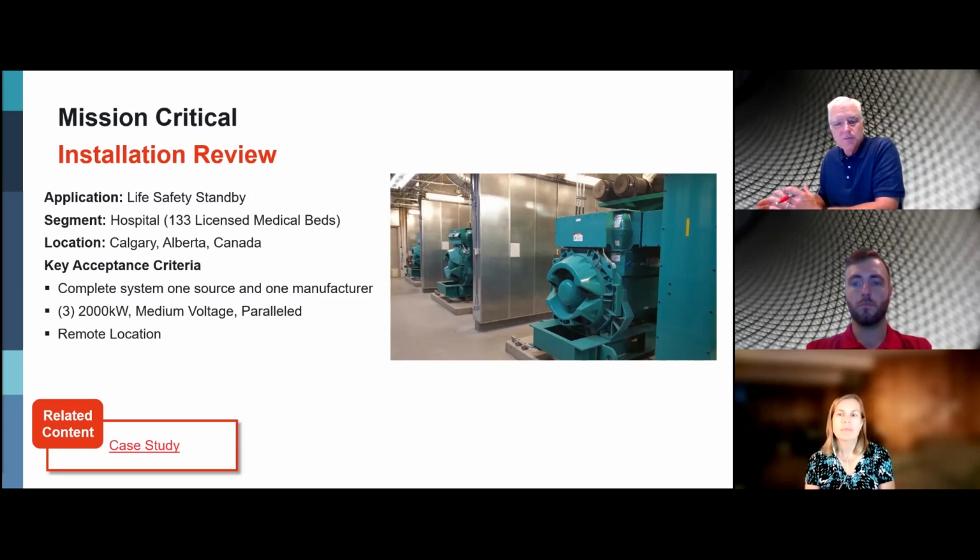All the testing performance exceeded expectations. CSA's Z32-04 standard requirements were met, with the 10-second interval in lieu of the standard's requirement of 12, which is different for the Canadian standards. Fuel capacity for this project was 50,000 liters, equivalent to 44 hours of runtime.